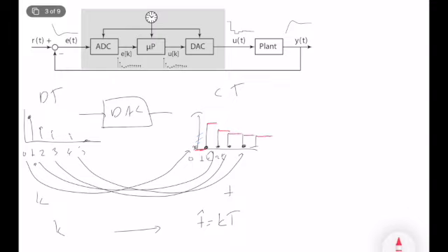Okay, so as you can see here and here, zero order hold looks like a staircase, right? Or a piecewise constant square wave function. Okay, so it's constant in between two sampling instants, but the variable changes when you get the next sample, or the next information from the microcontroller. So from 0 to 1, for example, t equal to 1 second, it is constant. At t equal to 1, you get a new value from the microcontroller. You change the output. It goes like this.